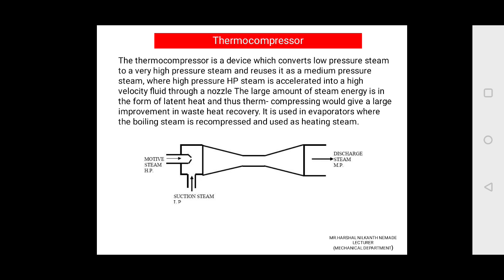Thermocompressor. The thermocompressor is a device which converts low pressure steam to medium pressure steam using high pressure steam, where the high pressure steam is accelerated into a high velocity fluid through the nozzle. A large amount of the steam energy is in the form of latent heat, and thus thermocompressor compressing would be a large improvement of the heat recovery. It is used in evaporators where the boiling steam is recompressed and used as the heating steam.